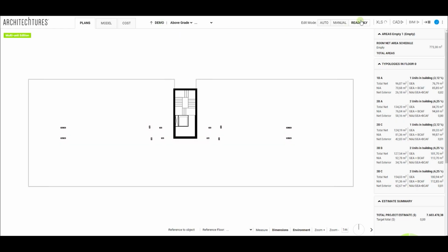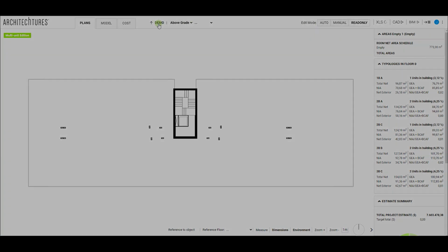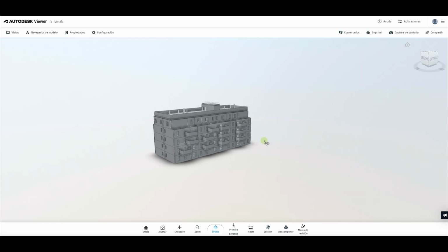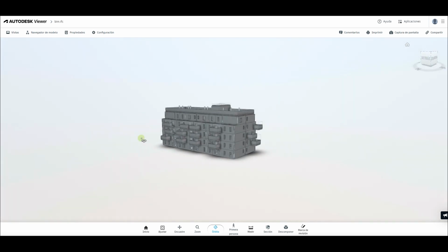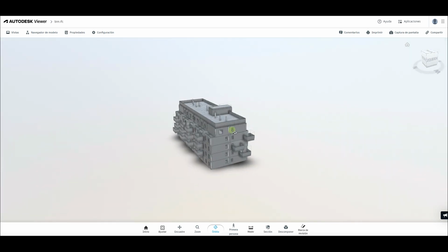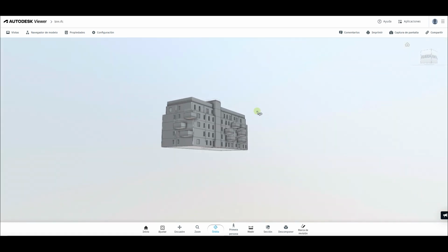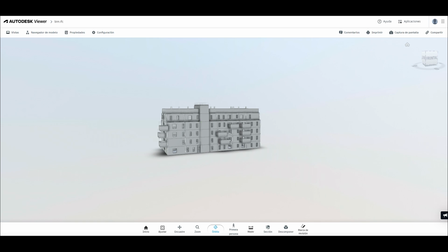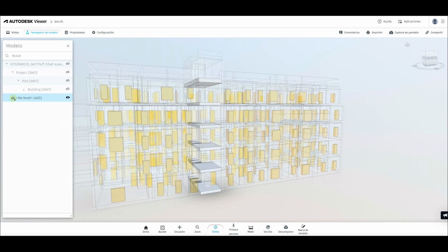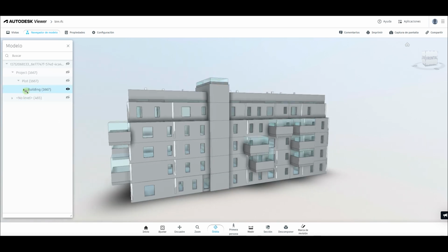The BIM model is an IFC file importable from any BIM editor or viewer. It is important to note that the thicknesses of the construction elements will be exactly as defined within the platform in the corresponding sections. Therefore, if we want to use the downloaded BIM model as a starting point to progress to higher levels of detail, replacing the default families with other more detailed families with layers or more information, it is important to generate the BIM model with the exact construction thicknesses of the families we are going to replace.